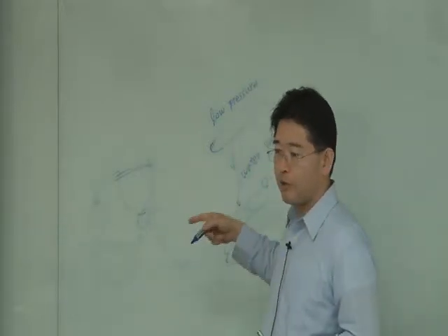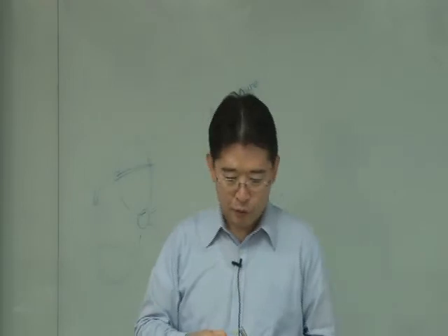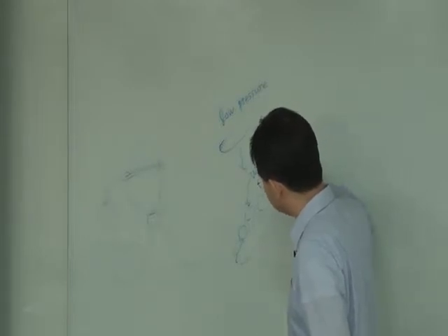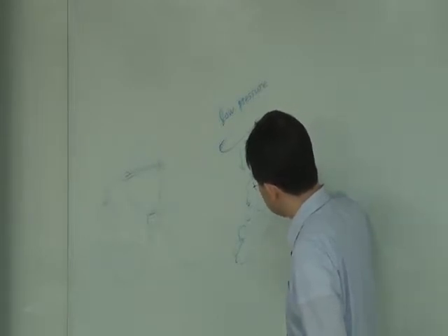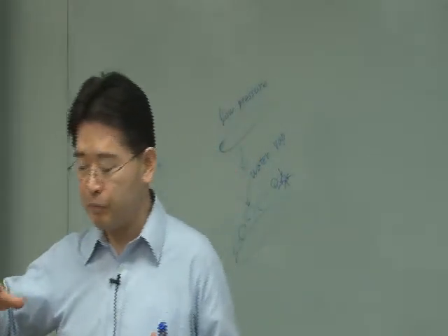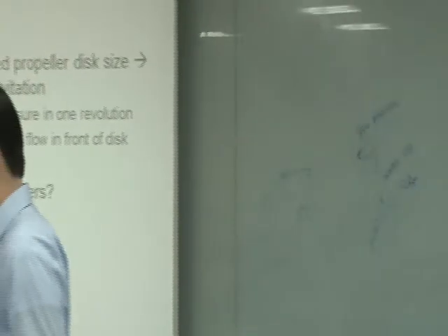It is at the temperature of normal condition, but it is boiling. And when pressure recovers, these bubbles collapse again, and when collapse happens, it will generate very high pressure.